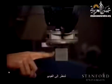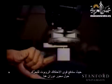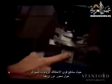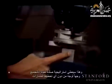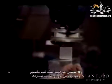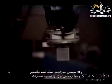So if we could see the video back. Here we are creating a strategy to do face-to-face assembly where the contact forces will drive the robot to move about a rotation center here. And that will result in a robust strategy to do face-to-face assembly without any planning of the trajectory.